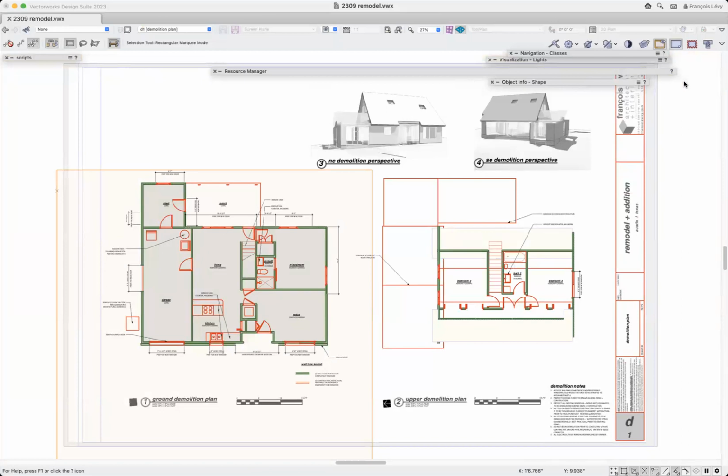Yep. I used to be really religious about showing rough openings in door and window schedules, and then for that very reason, that there were sometimes manufacturer changes. I found that a spec or a note that requires that they coordinate the rough opening with the manufacturer's requirements is maybe not as helpful, but probably more truthful. Well, it's helpful that they don't make mistakes.